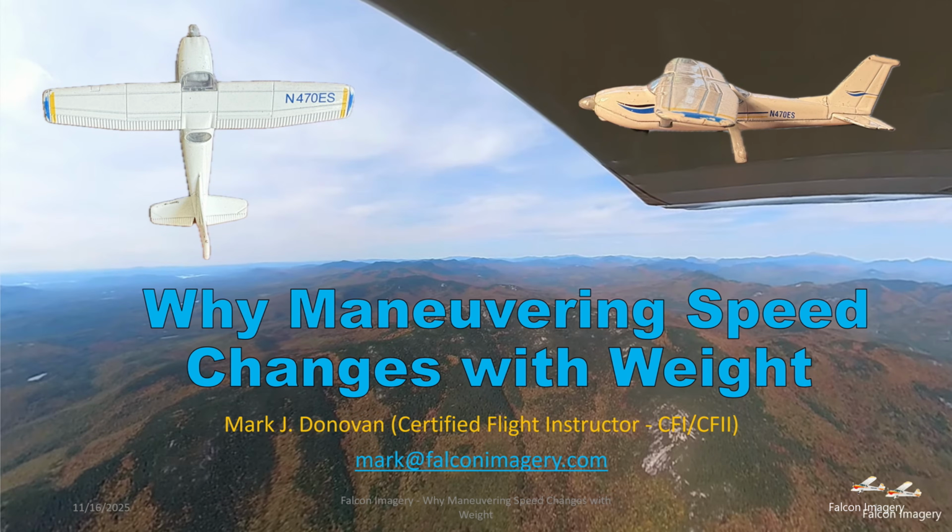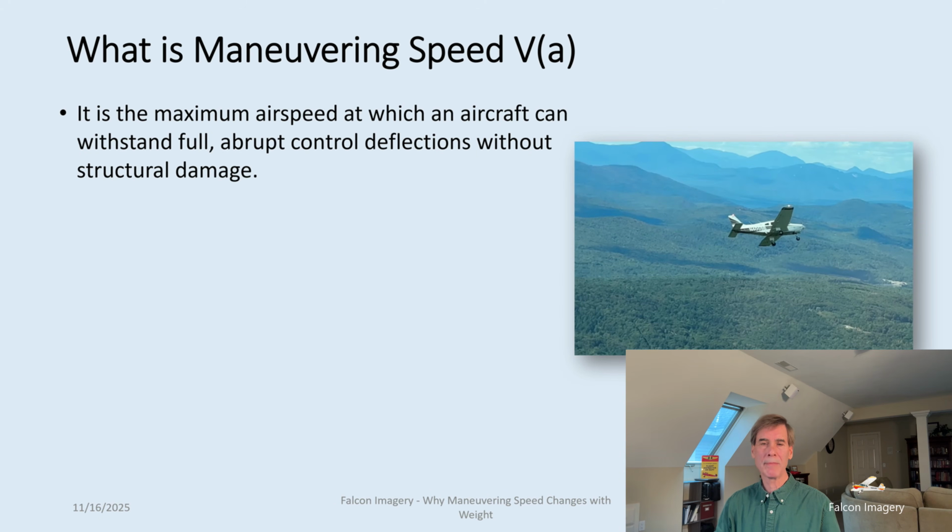Why maneuvering speed changes with weight and why maneuvering speed is so important for pilots to understand. So what is maneuvering speed? And by the way, the A in VA is for acceleration. Remember, force equals mass times acceleration. We're going to be talking a lot about load factors and gravity force. And again, force is a function of mass times acceleration, and that's why we have the A represented for our VA maneuvering speed.